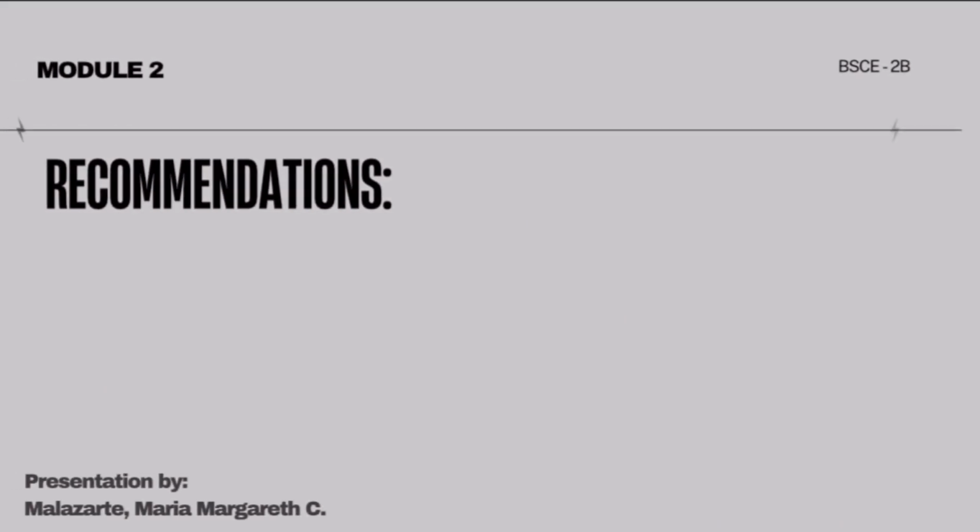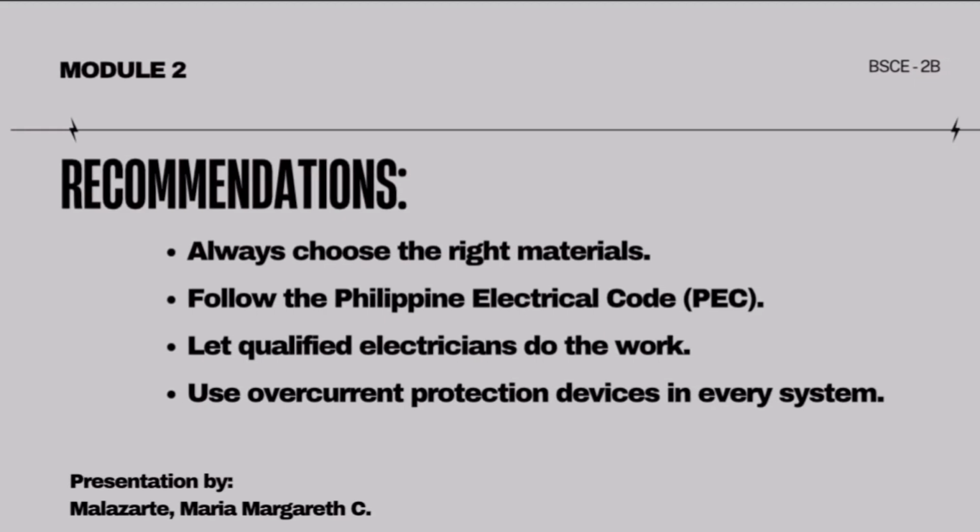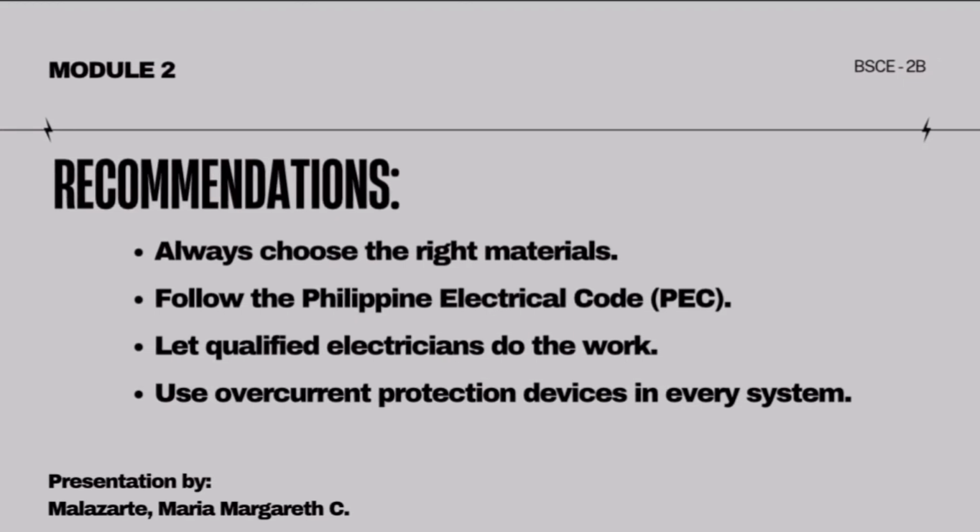Now, before ending this video, I will share some recommendations. First, always choose the right materials. Use high-quality wires, switches, breakers, and other parts that match the needs of the building. Don't use materials that are too small or not made for the job. They can cause accidents. Second, follow the Philippine Electrical Code, or the PEC. The PEC gives the correct rules for safe electrical installations. It helps avoid short circuits, overloading, and fires.